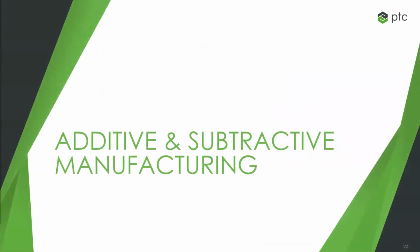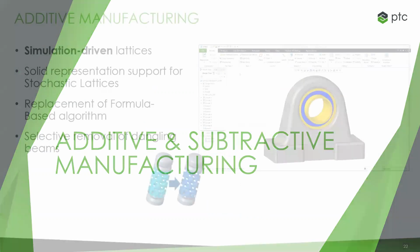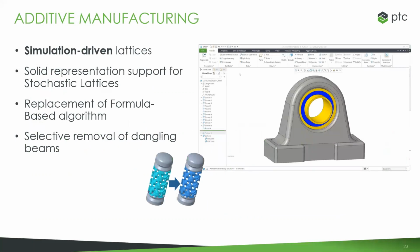All right, so the final area that we're going to move into talking about is our additive and subtractive manufacturing areas. First, we can go ahead and look at additive. This is, first of all, combining our design for additive manufacturing with our emerging technology around simulation-driven design. With Creo 8, we're really taking that to the next level by introducing the idea of simulation-driven lattices. Users can now leverage simulation results from Creo Simulation Live, as well as Creo Simulate, as inputs into that lattice creation. So whenever we're working with a model, we see any high stress points or low stress points in the model, and the system will automatically vary the density of those lattices in particular areas to get more of a uniform stress distribution.